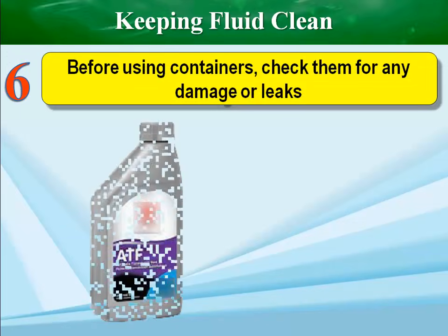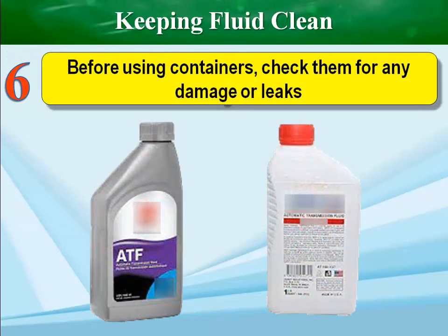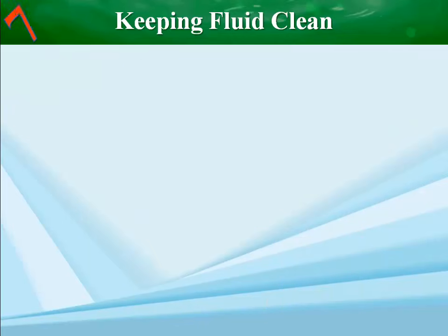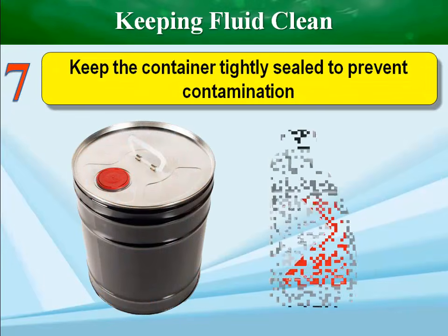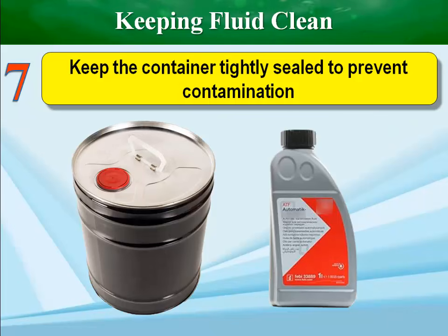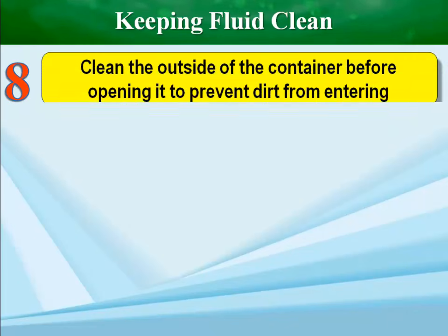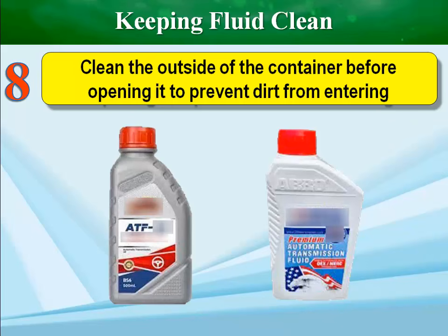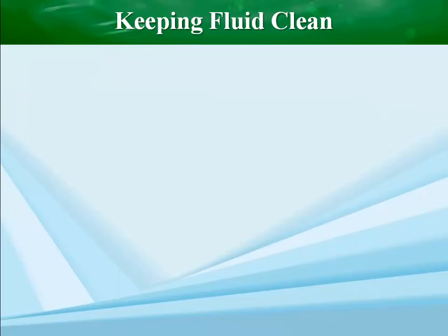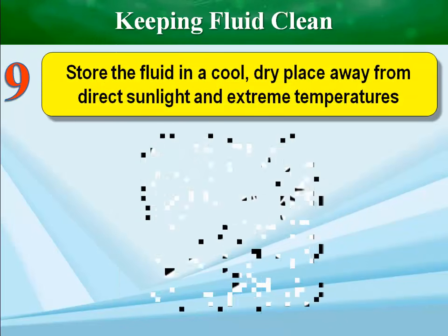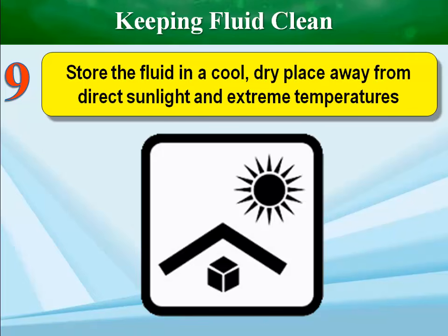Before using containers, check them for any damage or leaks. Keep the container tightly sealed to prevent contamination. Clean the outside of the container before opening it to prevent dirt from entering. Store the fluid in a cool, dry place away from direct sunlight and extreme temperatures.